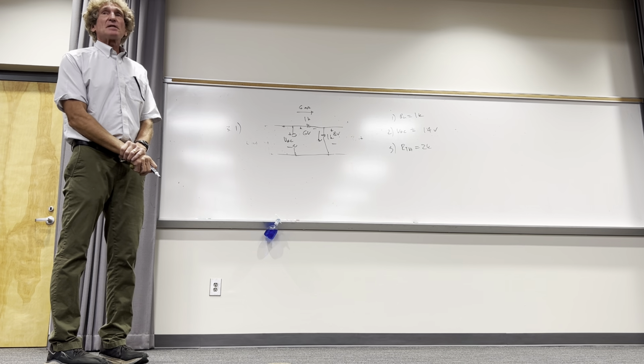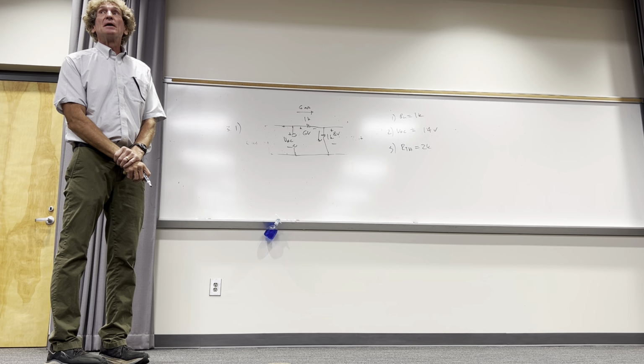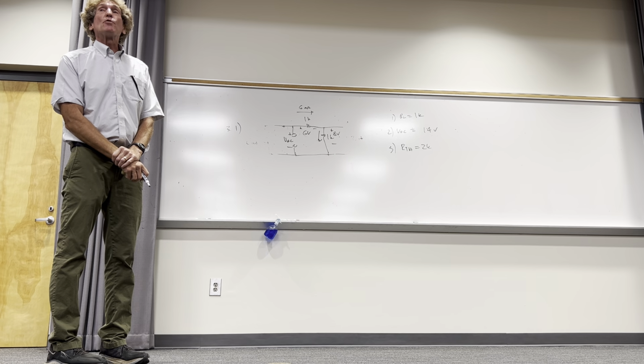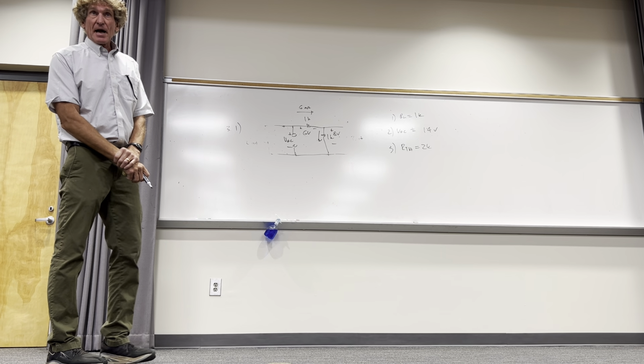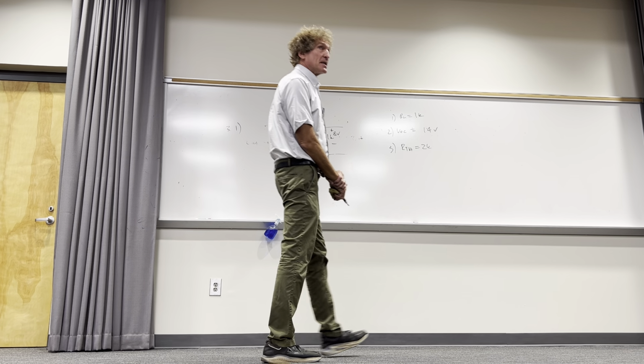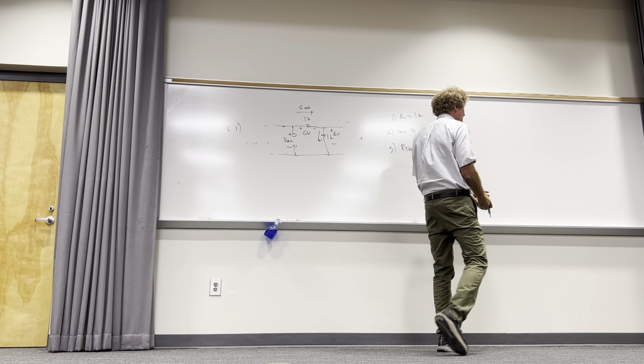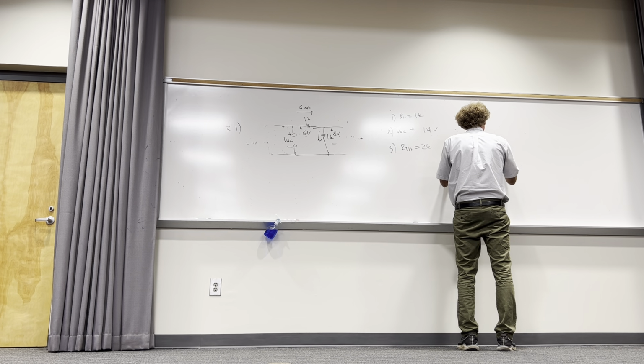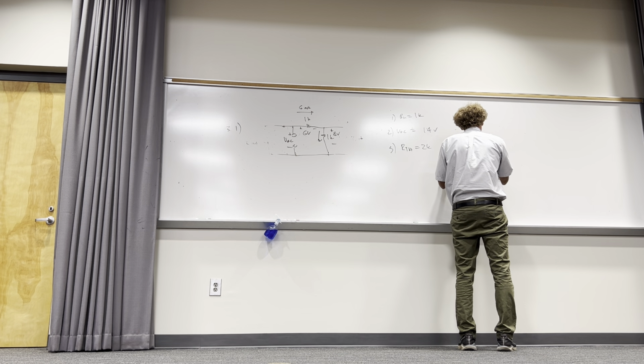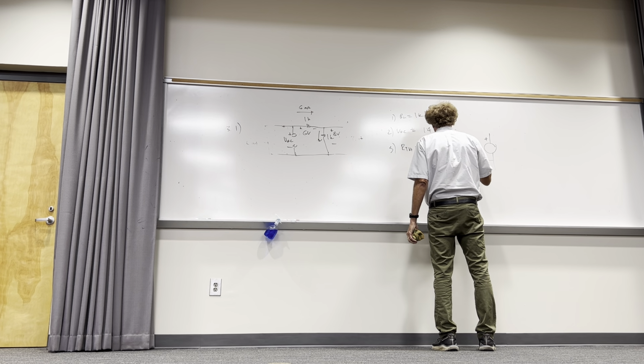All right, now what's the last step, class? We're going to assemble the equivalent circuit. Now, the Thevenin equivalent circuit doesn't have a load. Doesn't matter what the load is now. But now I put the V open circuit here, which happens to be 14 volts.